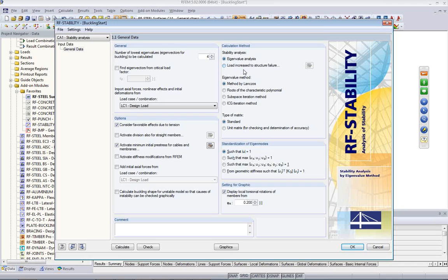The difference is that I also take into account force or stress redistributions during the iterations, failing members, and all those things are taken into account, while the eigenvalue analysis takes the axial force level from this load case, the stiffness matrix from this load case, and runs the eigenvalue analysis based on this, and there's no redistribution. Those are actually the 2 important features here.